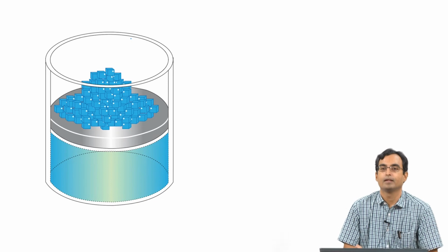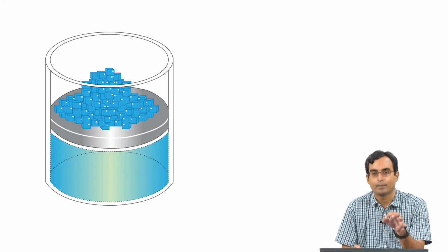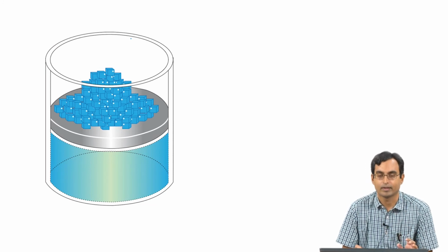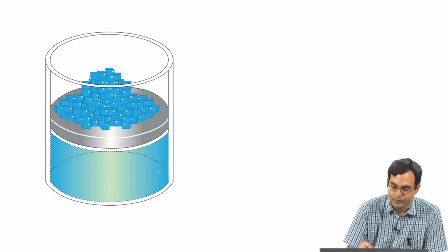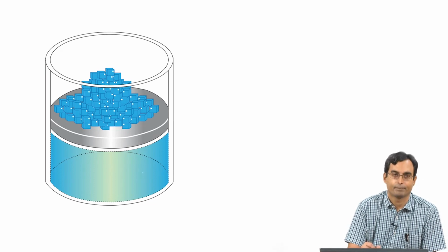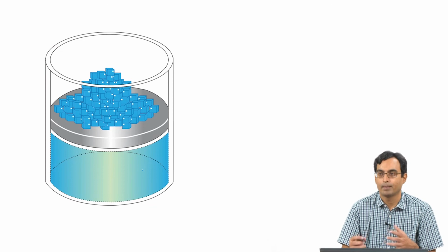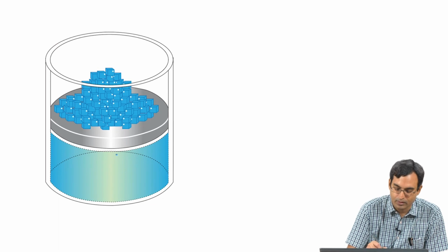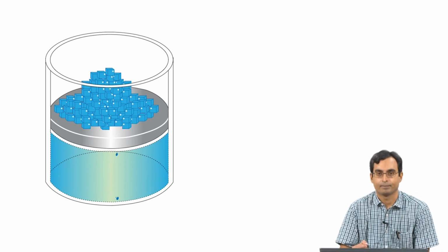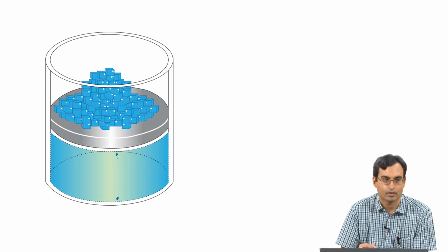So, this kind of a process is what we call a quasi-static process. It is almost static. The piston is almost not moving, but it is moving slowly. This would be what we call a fully resisted process or a quasi-static process. And in this kind of process, the nice thing is that because it is always in equilibrium, we can measure properties of this system. We discussed in the first lecture, when we looked at properties, that we can only measure them when things are at equilibrium, because, for example, if the piston is moving fast, then the pressure at the top and the pressure at the bottom may not be the same thing. If I measure the pressure here and here, I get different values. I do not know which represents the pressure of this system.